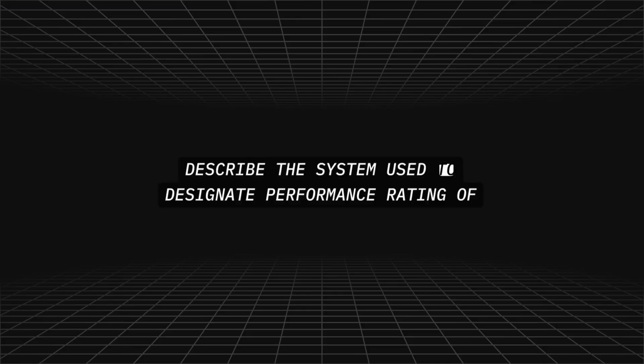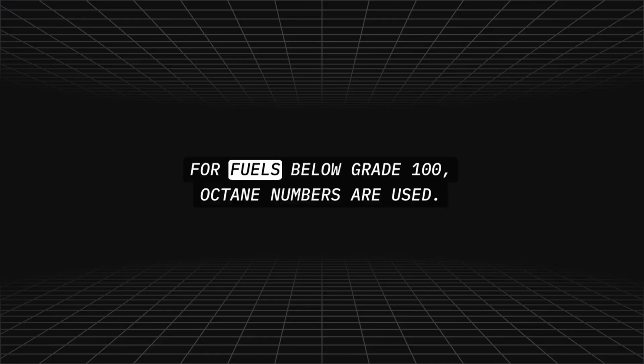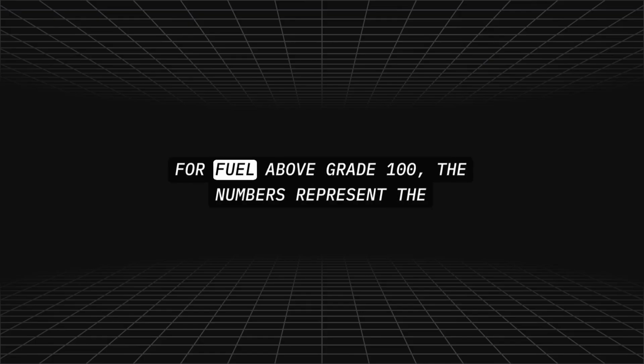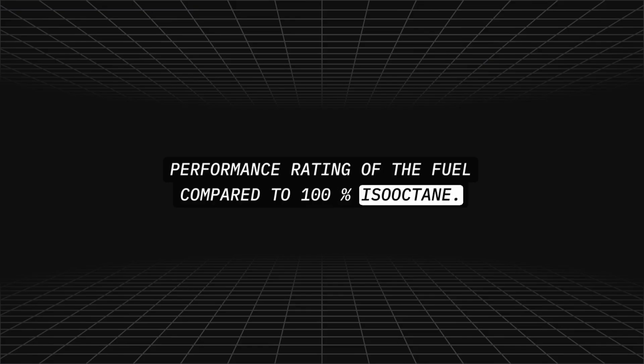Describe the system used to designate performance rating of aviation gasoline. For fuels below grade 100, octane numbers are used. For fuel above grade 100, the numbers represent the performance rating of the fuel compared to 100% isooctane.